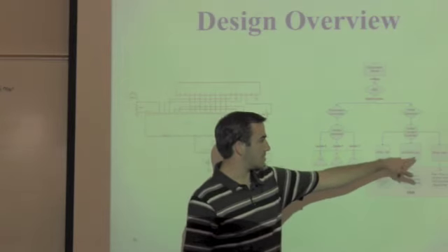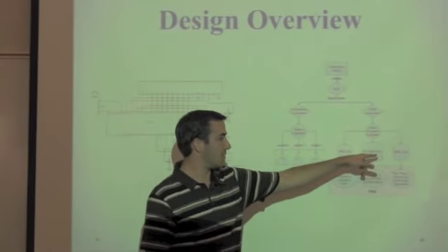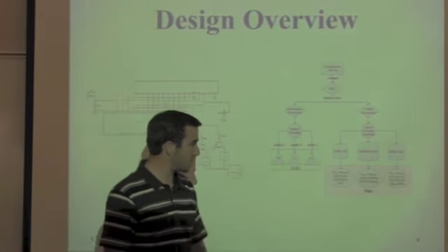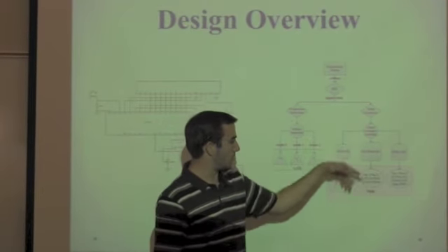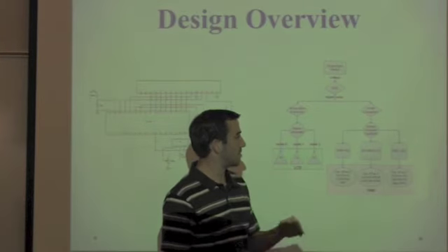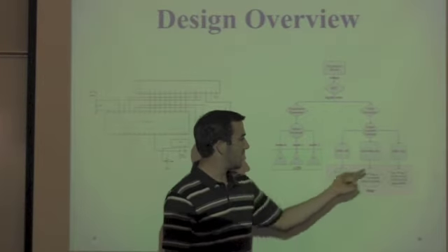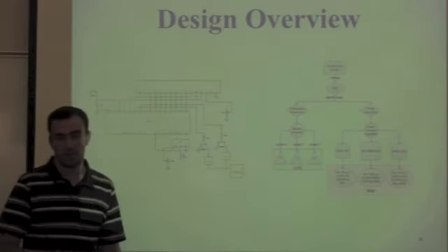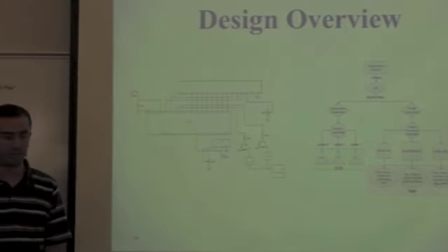Values between 60 and 255, which is the max OCR value, just get the pulse width modulation conversion value, and over 255 would just be the max, capped so it wouldn't overflow.